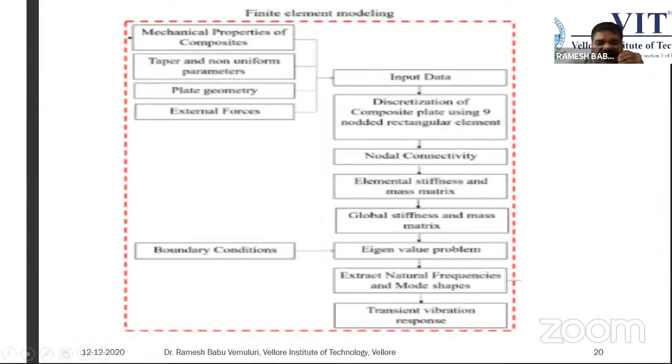So once you consider the 9 noded element, the 4 noded element or the 8 noded element, you consider that nodal connectivity, and we have to check whether this connectivity is continuous or not. Only if continuity is followed can we use that particular element, and if it is not there, then we need to make it continuous. The continuity should be followed. So once the continuity is followed, then we can substitute those displacement equations into the normal or the finite element composite equations.